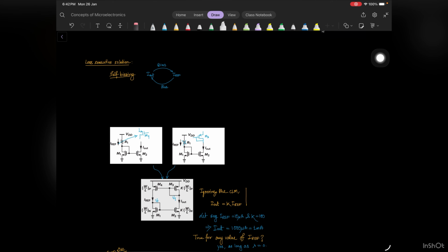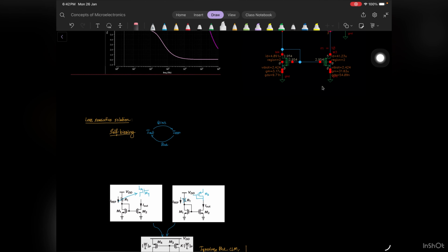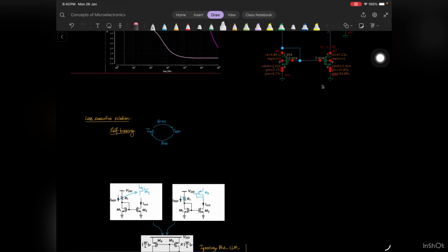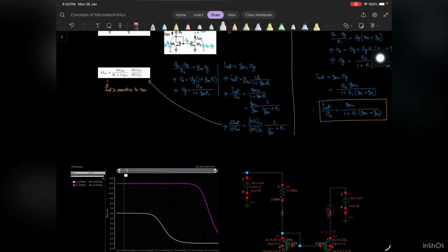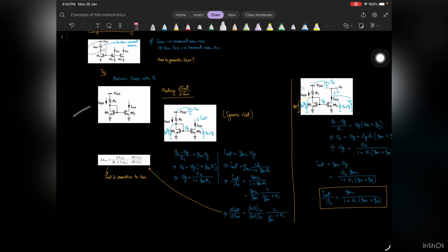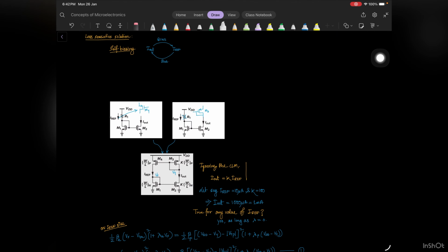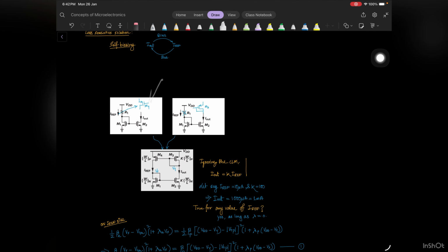Now what we are trying to do is improve the circuit. So here we are trying to obtain a much less sensitive solution compared to this case. So instead of deriving the IREF current from VDD and R1, we are trying to replace this R1 by a transistor called M4, and the reference voltage for M4 is generated by M3 from I out.